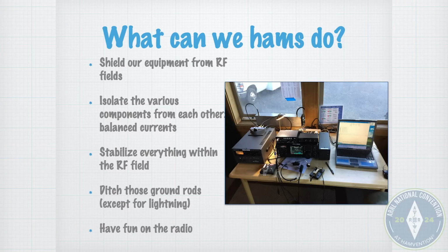So with that, what can we do as hams? Well, shield our equipment, as I mentioned. Isolate the things, sprinkle those ferrites everywhere, stabilize things within that RF field, and except for lightning, you can ditch the ground rods because they're a pain to deal with anyway. And then have fun on the radio because that's the most important part.